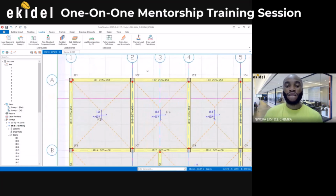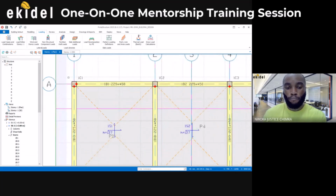Because basically, when we are doing a design for a structure, we are looking for the stability and also for the cost. Now, this thing we have done, which is hinging, has an impact on the cost. Since we have said that the moment here should be 0, that's a hinge end, it will just use a minimal reinforcement on that side.